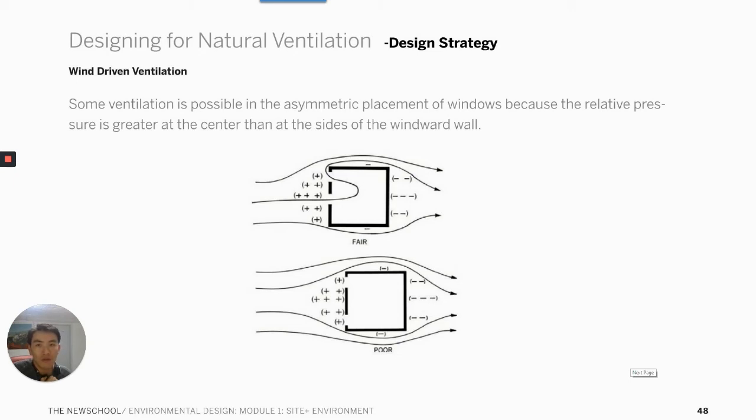In the upper case, even though both of the windows have positive pressure, the wind will blow in from the window that has more wind pressure coefficient and go out through the window that has less wind pressure coefficient. On the other hand, the below case shows where two windows with the same wind pressure coefficient will reject the air from coming into the building.